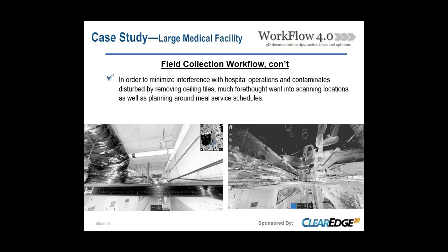So the workflow itself had to be customized to that end. What we did initially is we went around and scanned the corridors themselves as a baseline for our registration. Then we'd remove a tile. We'd hike the scanner up into, I guess you'd call it the breach, between the ceiling, the subceiling and the floor below, and we'd do a scan to capture data above and below so we had commonality, and then we'd do another scan up in the interstitial.